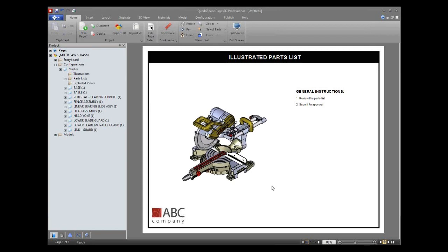Now, another handy trick is once you have your configuration set up, like I said, that's a quick way of doing it with the sub-assemblies. You can also add parts back in or remove parts by suppressing them. That's a topic for a different webinar. You can do that from this configuration ribbon. I'll just show you real quick. You have these suppress tools: suppress hidden, suppress tool, suppress selection. And then you have the opposite of bringing them back, unsuppress using the tree.